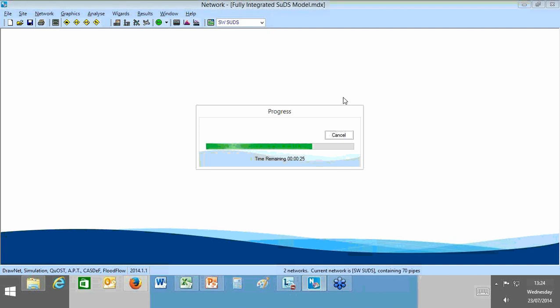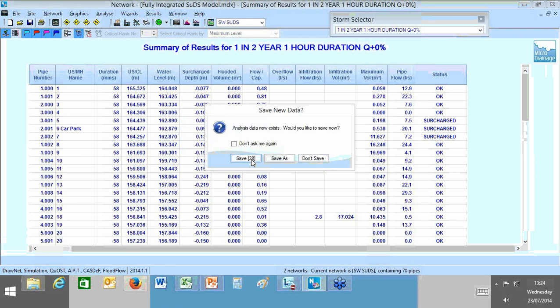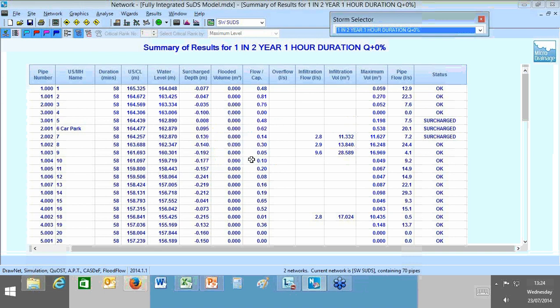Okay, we're being asked, can we test for blockages, etc.? Yeah, we can. What I'd do for blockages, to be honest with you, rather than using the sensitivity analysis, I would run with the additional rainfall intensities, but then I'd introduce an online control, for example, a weir up to the ground level that would effectively block the flow going downstream. Or we could add in sedimentation depths.